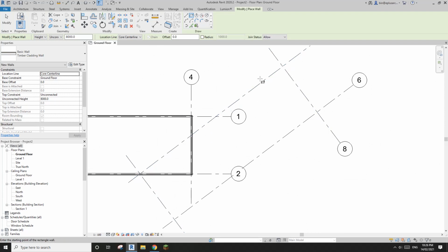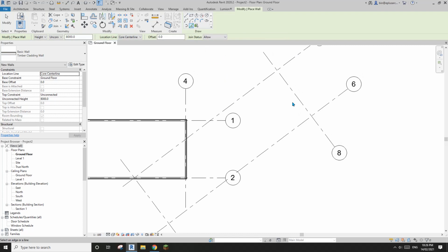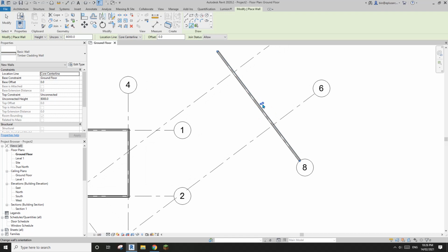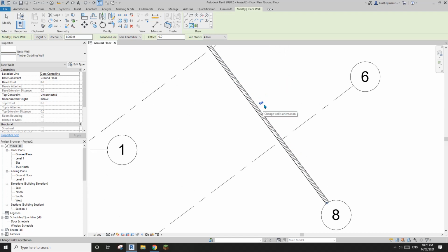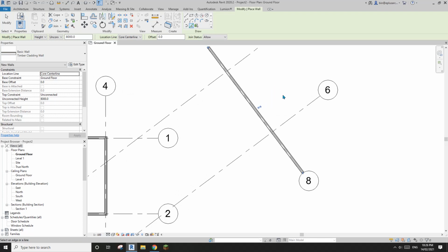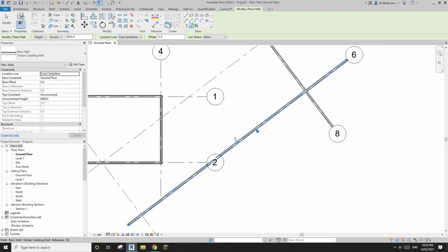This wall we won't be able to use this, we're just going to pick a wall. So now I'll just pick this wall, and if you see this one on this side, that's correct, because this needs to be at the external side, the exterior side of the wall. If you place it here and it's wrong, you will need to click on this to switch to that side.